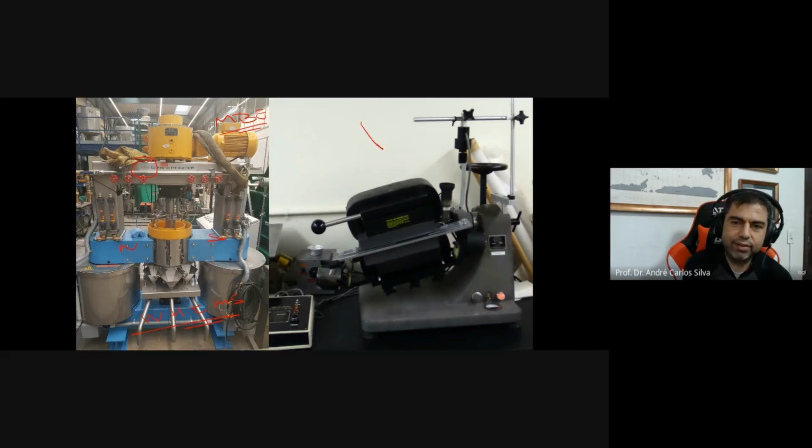But this guy over here, it's normally the favorite one when we talk about lab, okay? So this is called not Jones again, but Frantz magnetic separator. And how it works, I add material in here, okay? And this is my feeder. So the material is going to come out of it into this inclined plane over here, and I have actually two different angles.